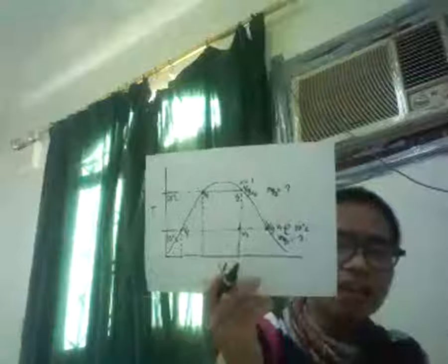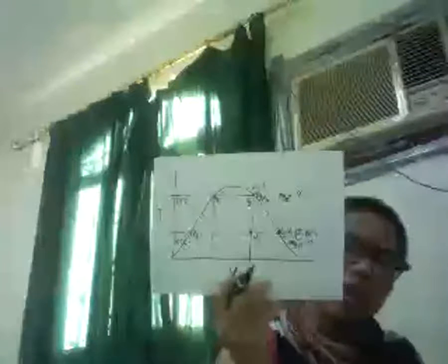Okay, so since this is a rigid tank, the mass will be the regular volume over the specific volume that we are trying to find out. So it could be the specific volume in 2 or the specific volume in 1 because, as I said, this is a closed rigid tank.